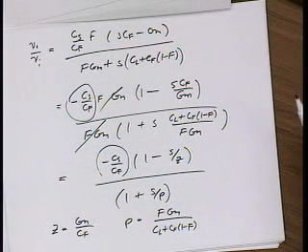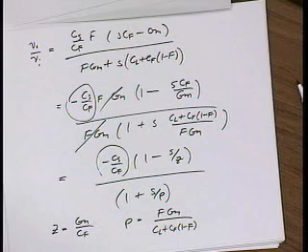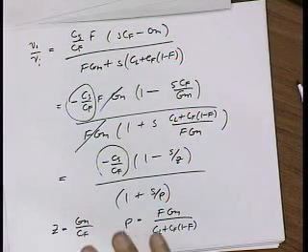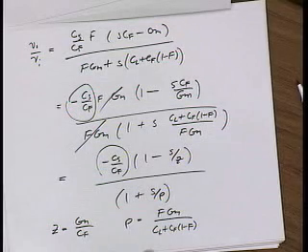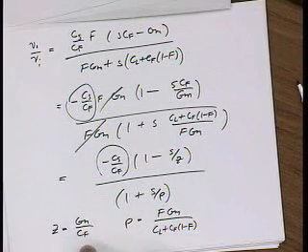Question: actually, GM has some frequency dependence because GM itself has zeros and poles. Yeah, you're absolutely right. But what we're going to do now is make a simplifying assumption that GM is constant. By looking at this equation, does it make sense that there should be a zero at frequency GM over CF?